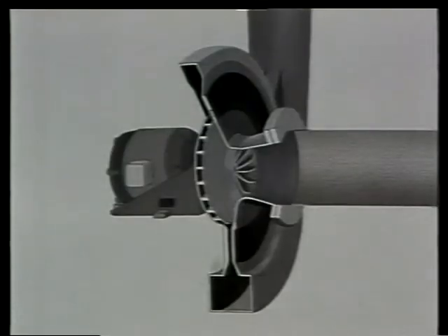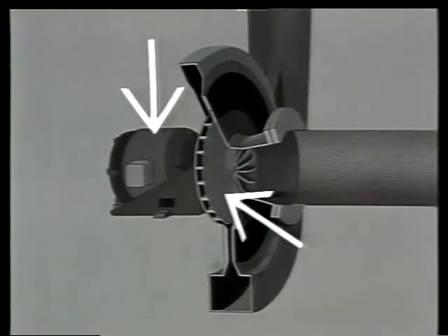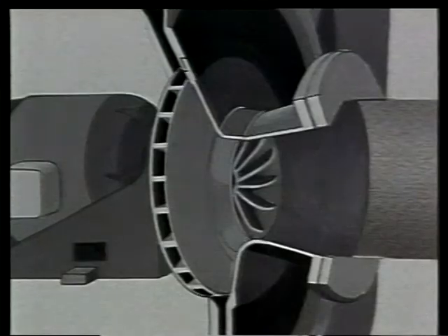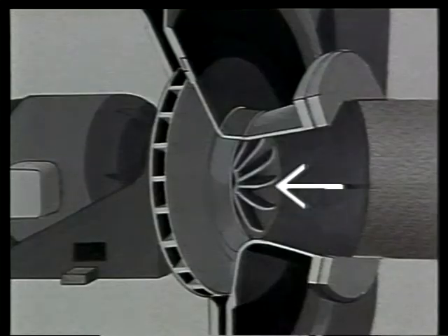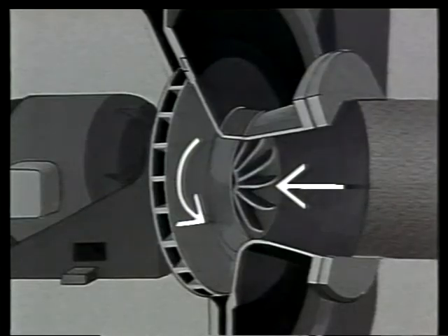Now, we're going to take a look at each of these different kinds and see how they work. To start, let's look at a centrifugal compressor. The only moving part in a centrifugal compressor is the impeller. A shaft connects it to a motor or another prime mover so that the impeller spins around during operation. In the center of the impeller is a set of small blades around an opening called the suction eye. When the impeller spins, these blades draw air into the compressor.